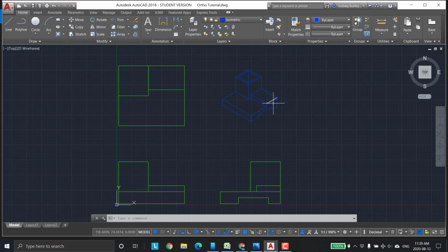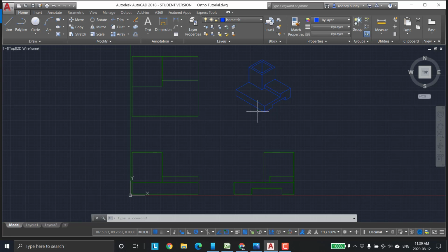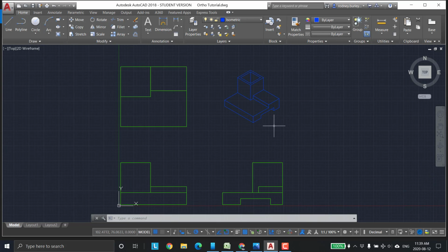You can. Now if I go in and dimension something right here, I'd have to change my dimensions to half size. It's also a good idea to put the scale of this right here because it's not the same scale as this. So a person that was designing or building this, they couldn't use their scale and measure this and say, okay, well, that's the size, right? So you have to be careful that way. Just put the scale right down in here or something.